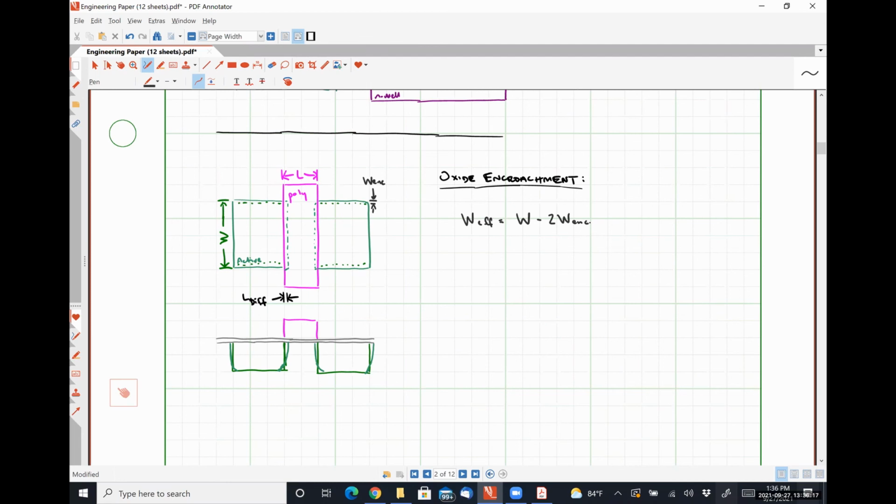So in the grand scheme of things, for a very large process like we're designing for, these effects don't mean a whole heck of a lot. If we were designing for very small transistors, short-channel processes, these things would be huge deals to deal with, right? 5 nanometers doesn't mean a whole lot when you're looking at 600 nanometers, but 5 nanometers could mean an extraordinary amount when you're dealing with a 14 nanometer process. So your gate length is 28 nanometers by design.